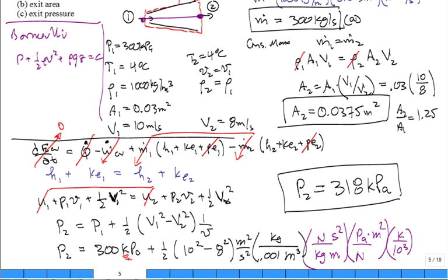A lot of hands went up. But is this the Bernoulli that you remember? They have it equal to the same thing on the other side. Well, that's what I meant by a constant. So you say along that streamline, state 1. First of all, are there changes in z elevation? So I'm going to knock that out. P1 plus 1/2 rho V1 squared is equal to P2 plus 1/2 rho V2 squared. Isn't that a correct application from state 1 to state 2 flow through this device?